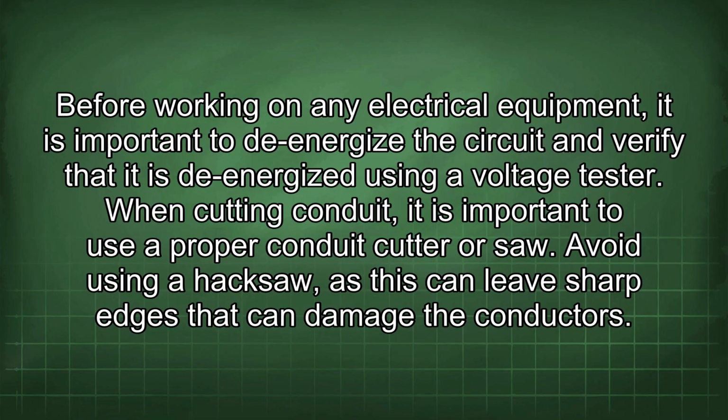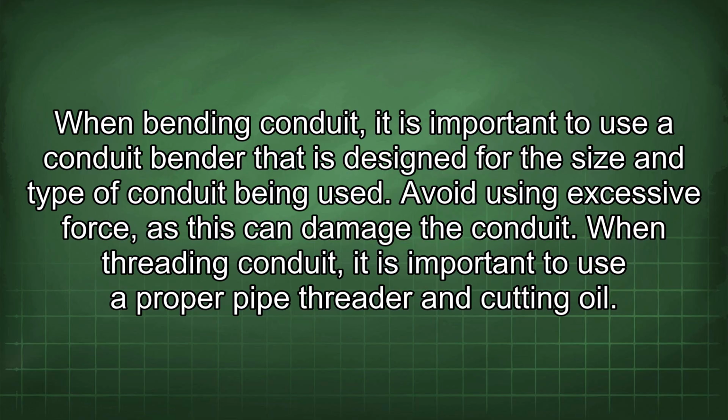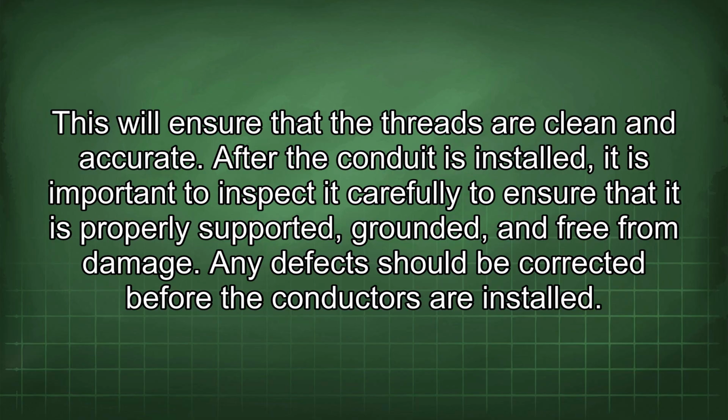a voltage tester. When cutting conduit, it is important to use a proper conduit cutter or saw. Avoid using a hacksaw, as this can leave sharp edges that can damage the conductors. When bending conduit, it is important to use a conduit bender that is designed for the size and type of conduit being used. Avoid using excessive force, as this can damage the conduit. When threading conduit, it is important to use a proper pipe threader and cutting oil. This will ensure that the threads are clean and accurate.